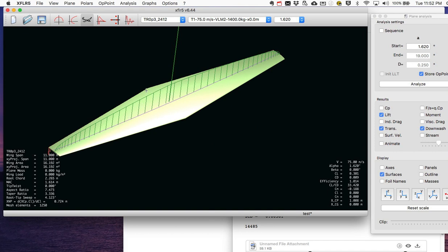A little higher at the root, a little smaller at the tip. This particular section is about 5 million. The other one's about 5 million. We're around the bending moment constraint, which means that we're not going to be able to drive the aspect ratio too far away from here. And so thinking about Reynolds numbers of 1 million and lift coefficients of about 0.3, what foils do well at those kind of Reynolds and lift coefficients?